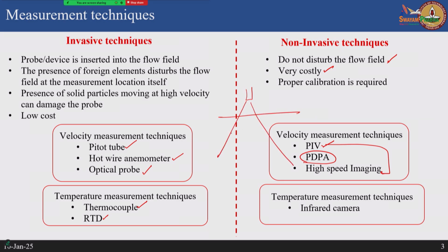Okay, now you have different planes along the length of the spray, along the nozzle length, and you want to measure what is the droplet size distribution and droplet velocity distribution at each plane, because this is very important to characterize the type of nozzle. So, different nozzles under different flow rate conditions can produce different quality of sprays. So, if you want to assess the quality of sprays, you need to first look at the high speed image, you need to assess what is the spray cone angle. That is the basic information that you get.